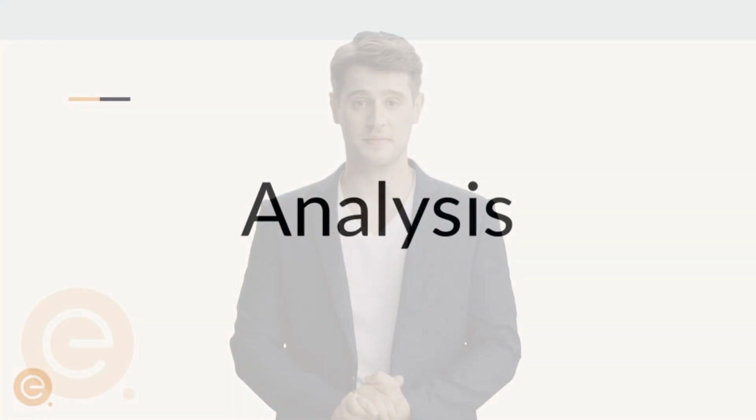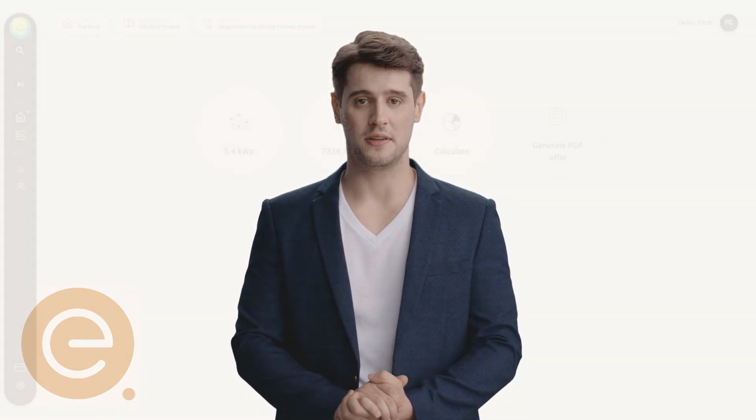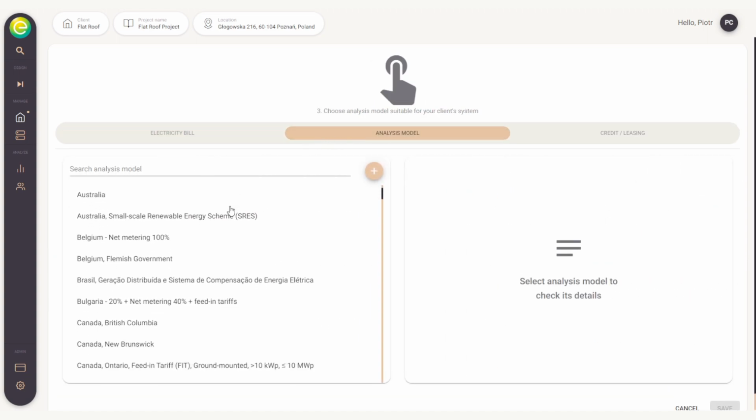Analysis. In this step, we're going to set the required parameters for solar calculation. First, let's start by inputting your monthly electricity bill. Next, adjust the price of electricity, projected annual price increase of electricity, and then profile of energy consumption. Move this slider to the right if your client uses more energy during the day, or to the left if it's the opposite. Next, click on the Analysis Model button.